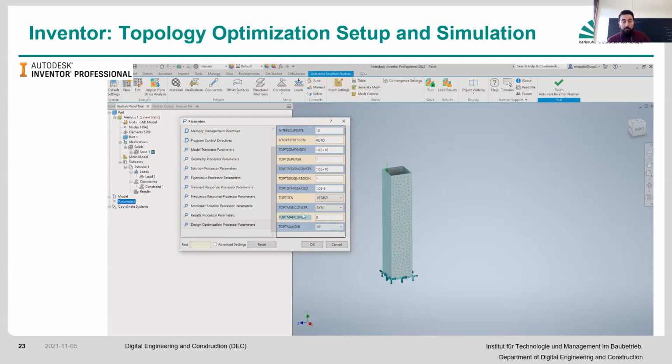the overhang angles. What the overhang angles essentially mean is that you have, let's say, an item that is going like this. Okay, it's completely hollow, and what ends up happening is, if you're doing additive manufacturing, we're going to talk about that when we get there, if it goes like that, then it's going to collapse. There's not going to be some support. So then you have to provide the support structure there as well, which is not really required if you can minimize that as much as possible.